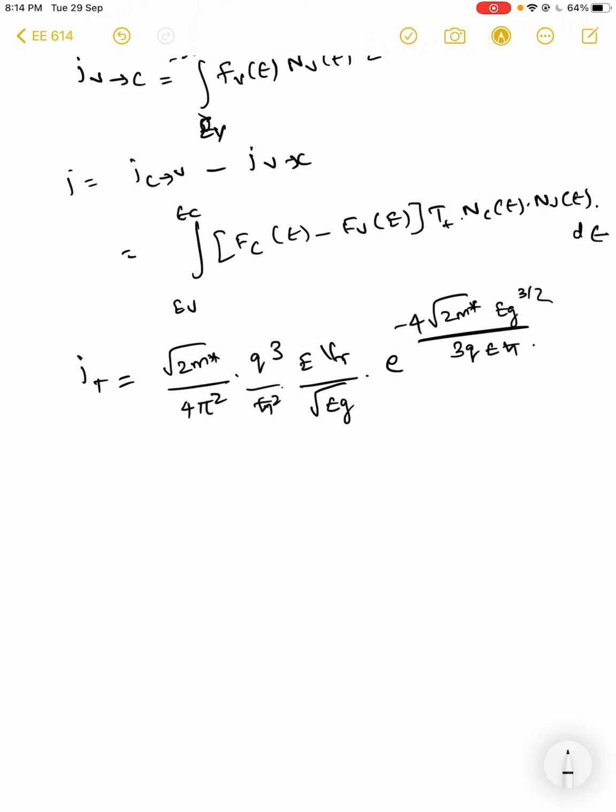The tunneling current depends directly on the reverse bias potential, which is easily understandable, right? The more the bias potential that you apply, the narrower the barrier becomes. You can easily see this from the diagram. Let us say that now I have a much stronger reverse bias potential, right? So now you can see that the bending in the band is now much more severe. Now this leads to the width being much smaller, but then having a much higher triangle, right? So the tunneling probability is dependent much on the width, and hence you will have a much higher tunneling current at higher reverse bias.